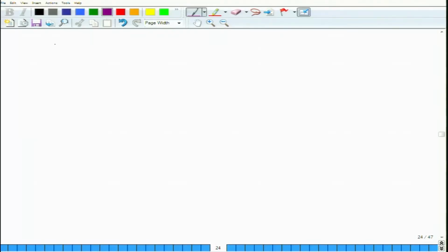So the next phase is that we will develop relationships between Ey, My and Nuyx and the special orthotropic material properties, which are El, Et, Glt and NuLt.